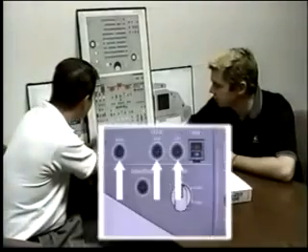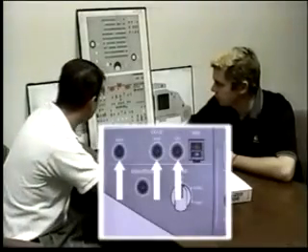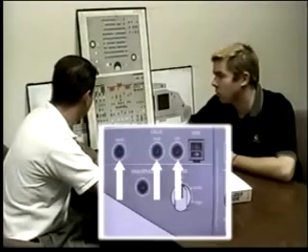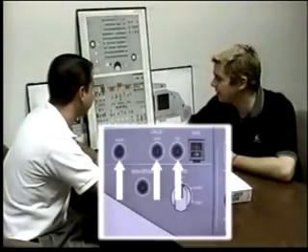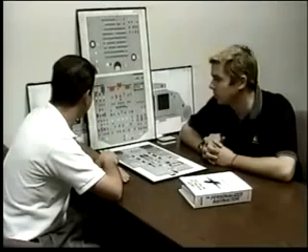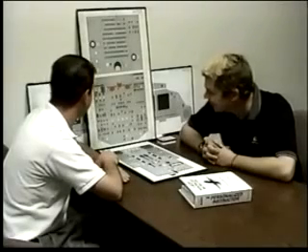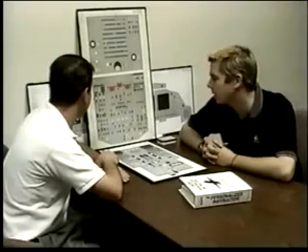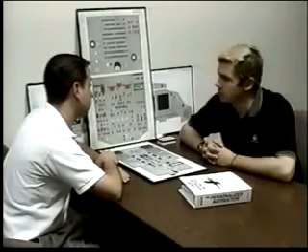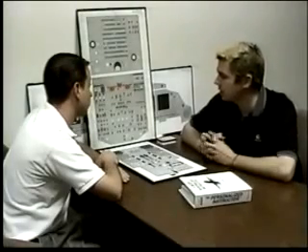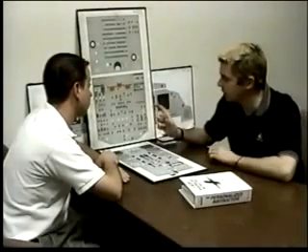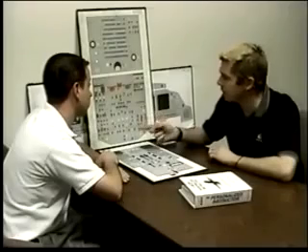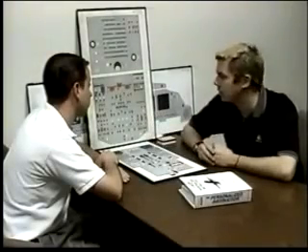Calls. Describe to me the mechanic forward and aft call push buttons. The mechanic is just a horn down below, and it lets the mechanic know that you want to talk to him. So he'll come over and talk to you. The forward and the aft is for the cabin. If I press the forward, they'll get a single ding, and then at the flight attendant panel up front, it'll say that I've got a cabin attendant call, and they're going to answer the phone.